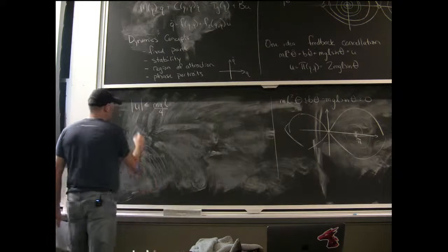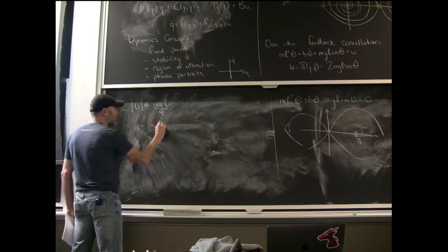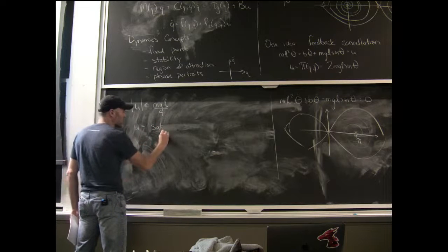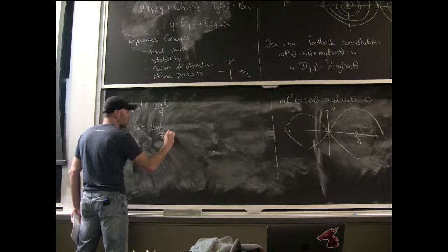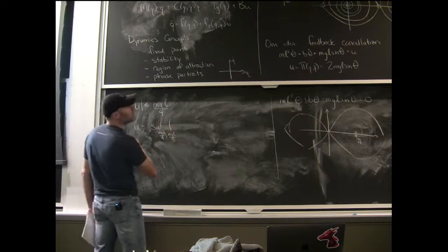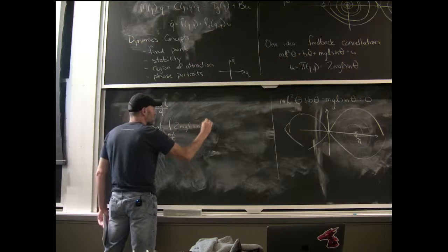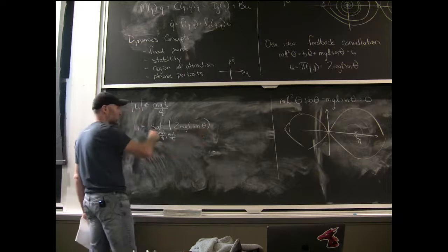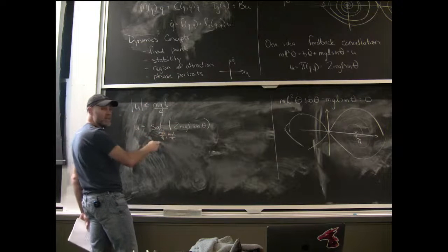So maybe I'll write that as u, we often use the saturation function. We'll say it saturates at negative MGL over 4 to MGL over 4 of this other controller of 2 MGL sine theta. So I'll compute this, and then I'll just truncate it. If it's greater than MGL over 4, I'll make it MGL over 4. If it's less, I'll make it negative.